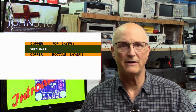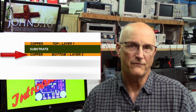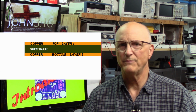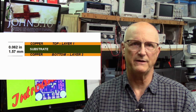Now, let's add some more complexity to this by putting another layer of copper on the top of the board. So now we have a layer of copper on the top and a layer of copper on the bottom, forming a 2-layer PC board. The most common overall thickness for a PCB is 0.062 inches or 1.57 millimeters.